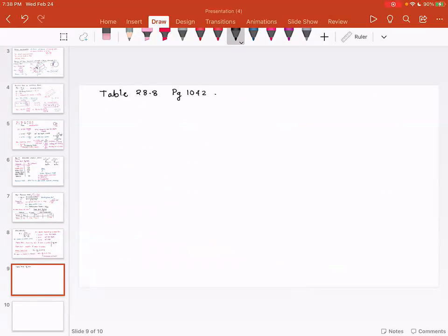One thing I want you to understand is that steel can be heat treated, which means you can heat the steel and cool it at different cooling rates, and that would change the surface hardness. That change in the surface hardness will affect the endurance limit.